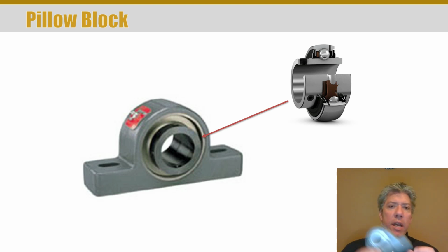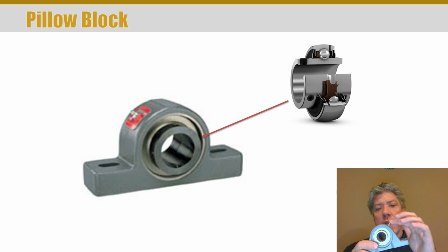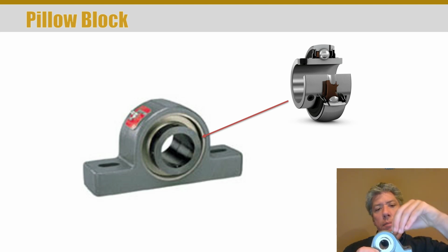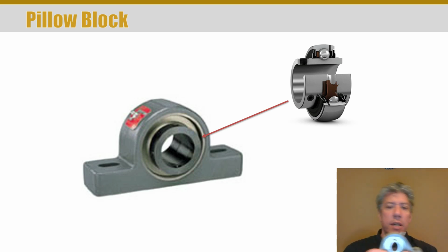Now one big problem with these things, and something you should know about, it's very common to introduce dirt into the bearing by greasing, because typically in a machine environment you're using them in a dirty, dusty, whatever environment, and that dust and dirt collects on the top of the fitting, and as soon as you put the mating grease gun onto it and squirt it in, all you've done is push dirt and grease into the bearing.